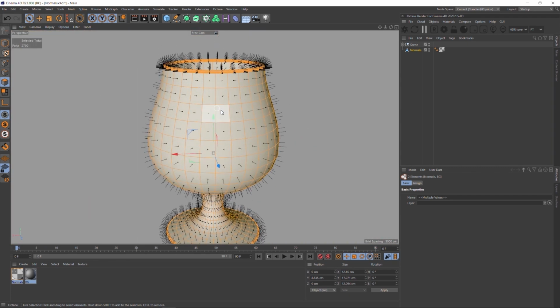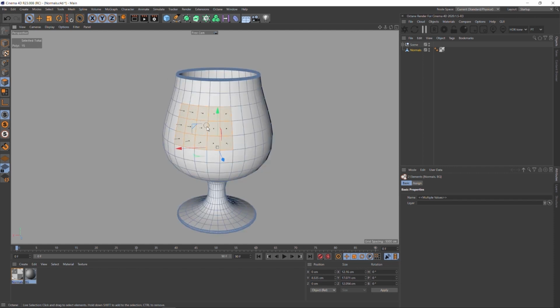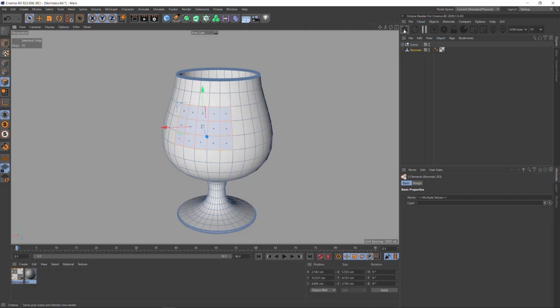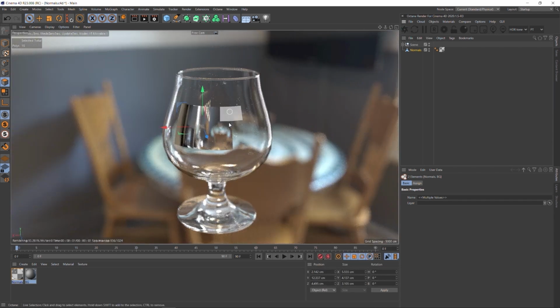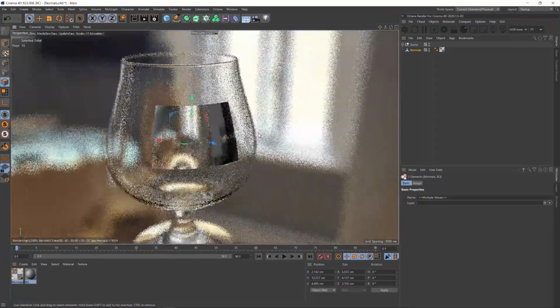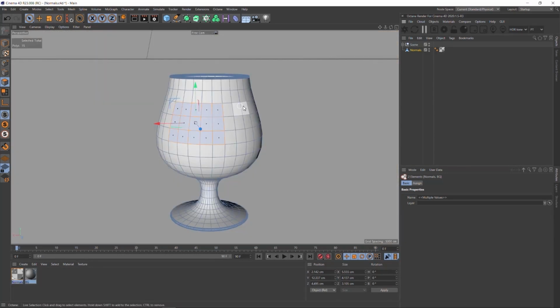So another issue that you could run into with this as well, and I've had it happen, especially with CAD models, is a portion of the normals are facing the wrong way. So let's take a look at what you see when you get that. Now, the renderer doesn't know what to do, how to bend the light correctly, because it's not hitting the correct side of the surface first. So let's go ahead and show you how to fix just this issue.